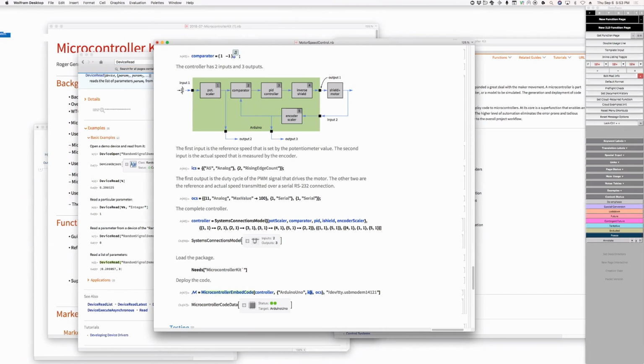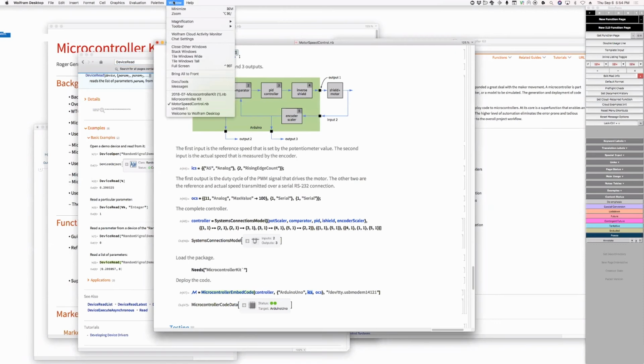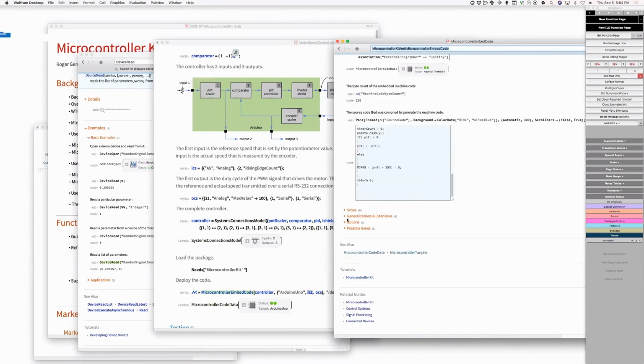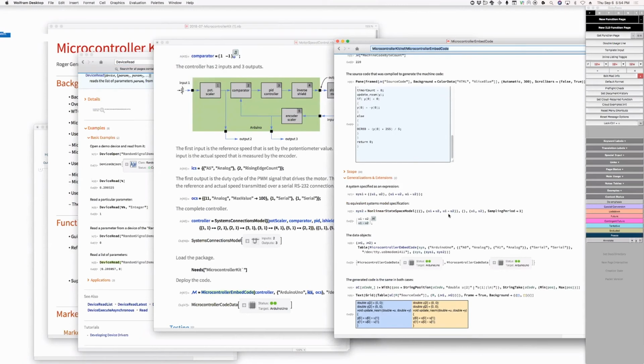So when I represent this controller, the only way I can do it is through this essentially matrix technology of transfer functions. Is that correct? Yes. Oh, I'm also allowed to just write a mathematical expression, like U1 plus U2. Well, for what operations can you do that? For things which don't have memory. Actually, if you look at microcontroller embed code in generalization and extension, I show that. It's a very limited set of operations, Stephen.